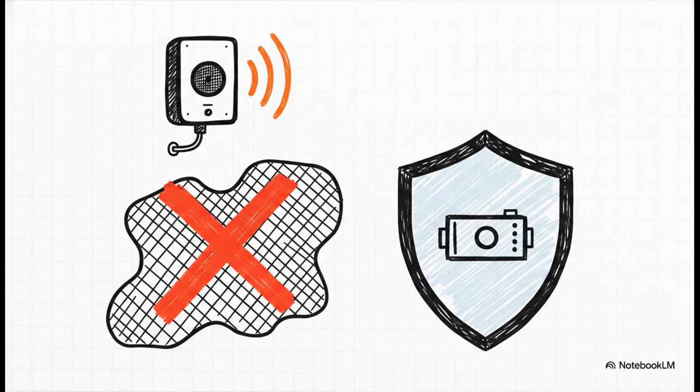Don't get me wrong, fixed gas detectors are fantastic tools. They alert operators, they sound alarms, they can even automatically isolate equipment. But they are strictly an auxiliary backup protective layer sitting on top of your classification. They never substitute for doing the proper ventilation calculations from the start.